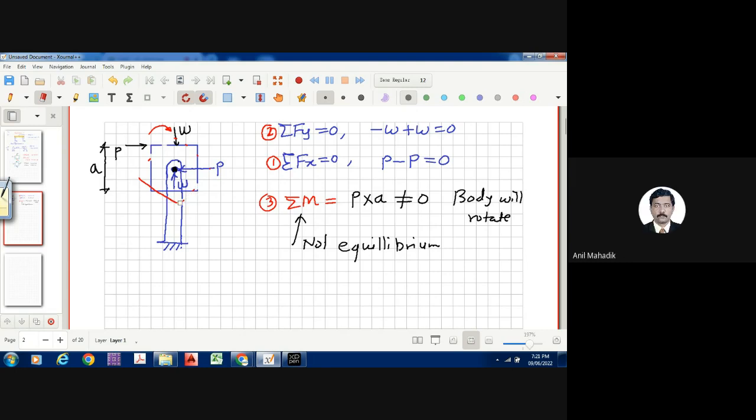But that is not a right solution, I think, because whenever we have a bolt, it has a very small diameter, isn't it? So even the weld will try to rotate, as it is very small. If it is a very big portion like this, if you prepare like this, I can say okay, your solution may be correct. So same load we will put on the right hand side, lower end. Yes, that will be a good solution.